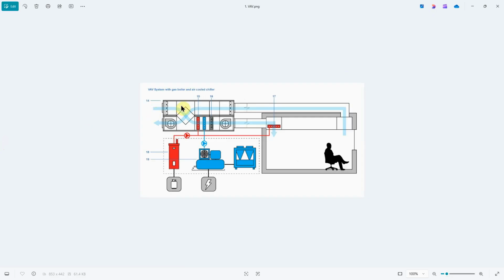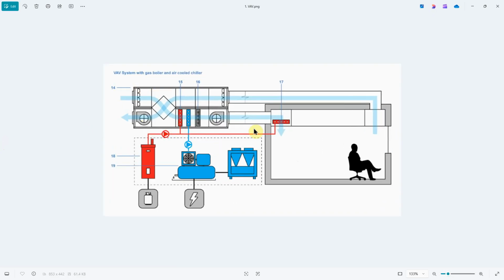And that's because they are. They all have this big box up here, and this is the air handling unit. We're bringing in fresh air here, exhausting stale air. These are blowers, right? The fresh air comes in, goes by the heat exchangers. In the VAV, we have a boiler and a chiller. This is a cooling tower that's probably on the roof. Those temperatures are supplied to the heat exchangers, and then the temperature is delivered to the zone. There's a reheat here so that we can have a control that's specific to each zone, each room if we want to. And then we have a return coming back. Very simple.